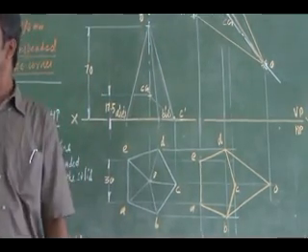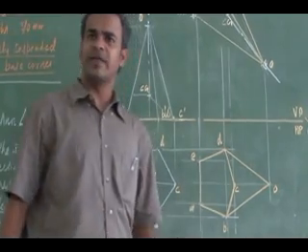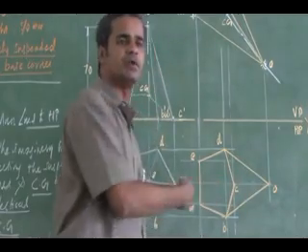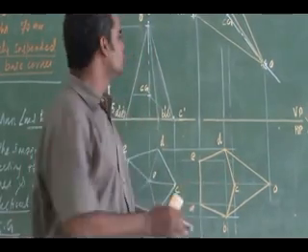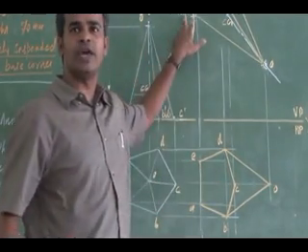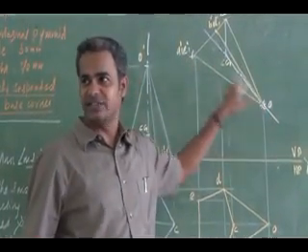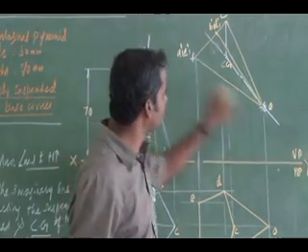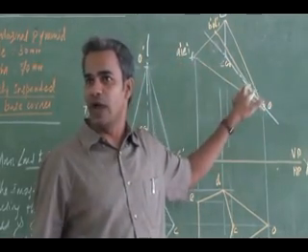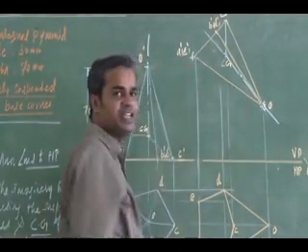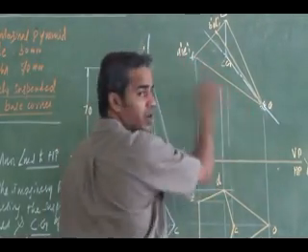Now listen. As per the other note, the side edge or slant edge which is going into the fully visible base is going to be hidden. Below the axis, the lowest slant edges will be hidden. Which ones are they? AO and EO.